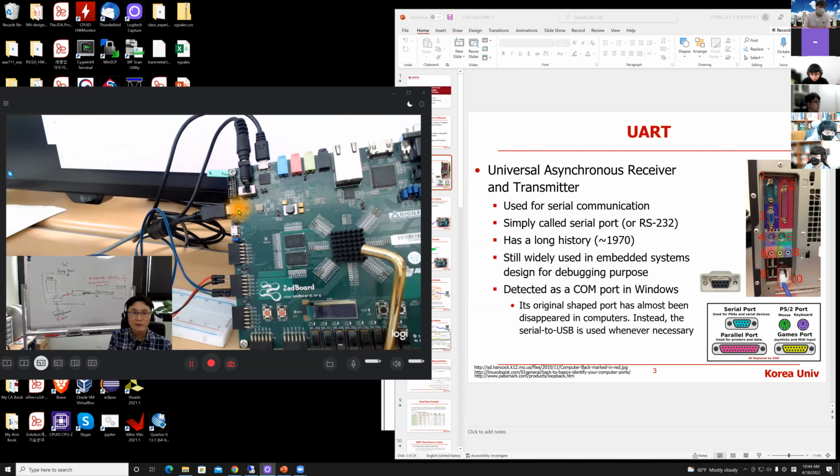There is a marking called UART, right? That connection is used for UART communication, and this other connection is used to download hardware and software to the board through the JTAG connector. Hardware goes to Zynq, and software goes to the main memory, right? So that is serial communication.